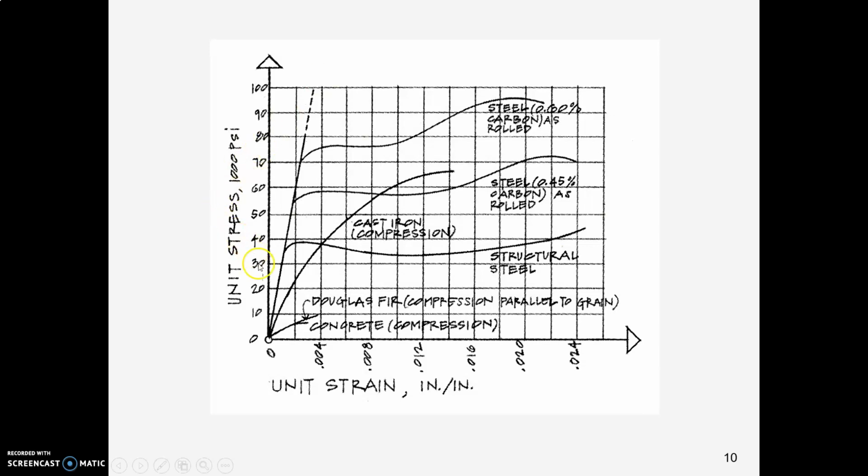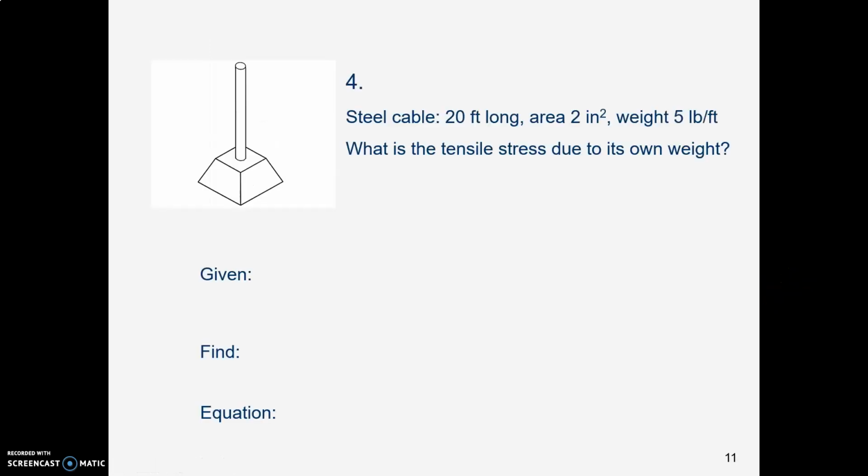What makes a material like mild steel be ductile is that it has an elastic range and it gives warning. Things are starting to stretch. It gives warning before it yields, but cast iron doesn't. The yield range is so small you don't notice it. Well, anyway, let's go on to the next quiz question.